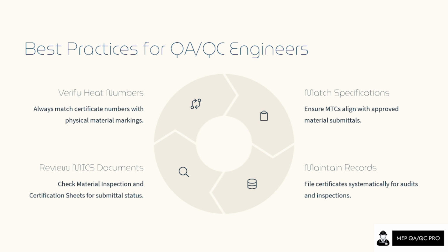Then you will maintain that record. You have to make your own test certificate log, showing that whatever material arrives at site has been quality checked by the supplier and the manufacturer, and that the certificate is valid proof for the delivered material.